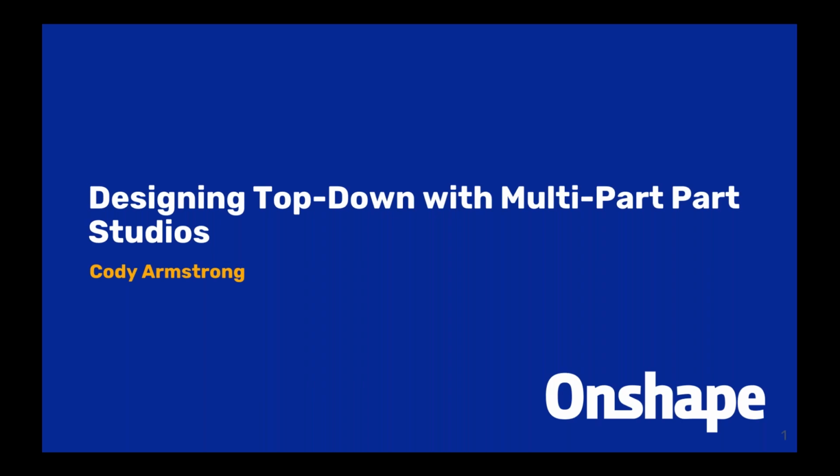I also want to spend some time today discussing the way this has been done in older CAD systems. I think there are a lot of users out there that veer away from top-down design in a multi-part environment in Onshape because of the multi-bodied nature of past CAD systems. So I want to go over some of those details as well, and discuss how what we have in Onshape multi-part part studios compares to multi-body systems of SolidWorks and things like that. So, designing top-down with multi-part part studios.